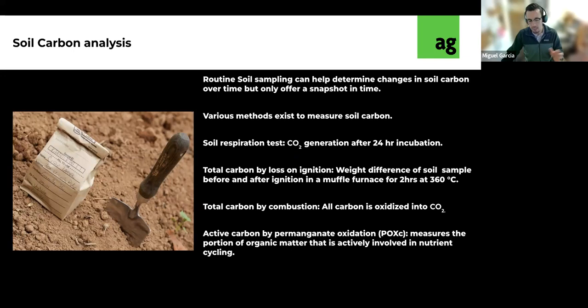The key is that you need to make sure that you have a very thorough representation of your field, in that every sample is collected at the same depth and that you're collecting the same amount of soil. Because if you go and collect more from one region than the other within your sampling area, that could also create discrepancies. So the benefit of this method is that you develop an average of what that field looks like.